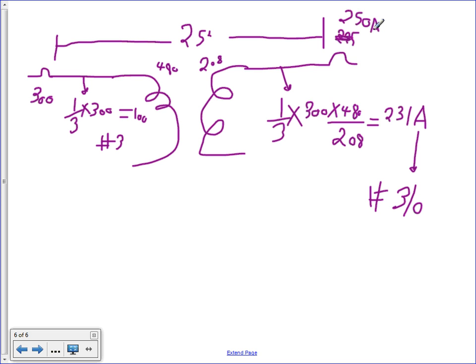What is it, 4/0 or 3/0? 3/0 is good for 200. 4/0 is good for 230. Then this is 4/0. And what's 4/0 good for? 230. Then this will shoot 225. I thought you guys were helping me. Okay, right? Are we good now? So 4/0, I'll give you 225.